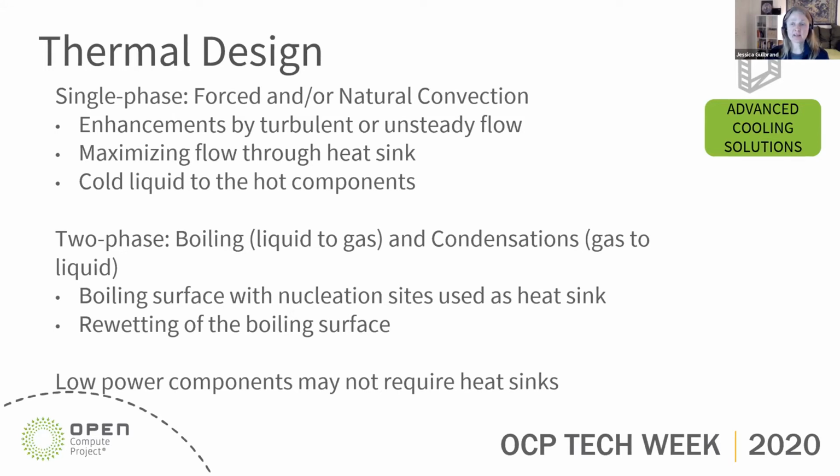For two-phase, we're dealing with a slightly different phenomenon. We're dealing with boiling, so we have the liquid to gas phase change transporting and getting the heat away from the hot components. And then you have the condensation of gas to liquid on the top of the tank, if we're talking about tank installations here, and the liquid is dripping back into the tank again.